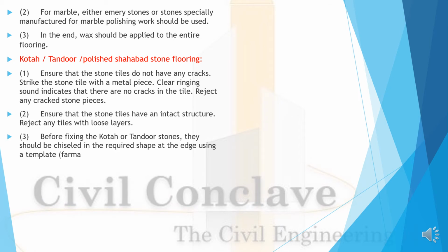Ensure that stone tiles do not have any cracks. Strike the stone tiles with a metal piece. A clear ringing sound indicates that there are no cracks in the tiles. Reject the cracked pieces. Ensure that the stone tiles have an intact structure. Reject any tiles with loose layers.